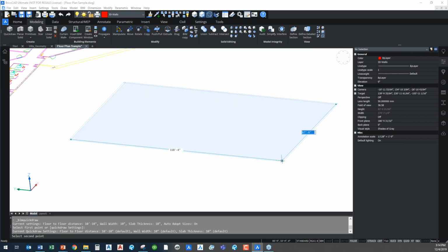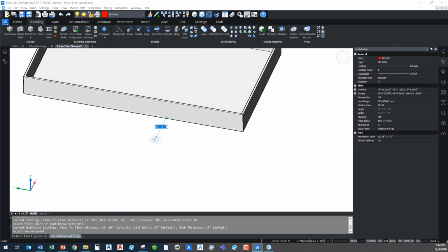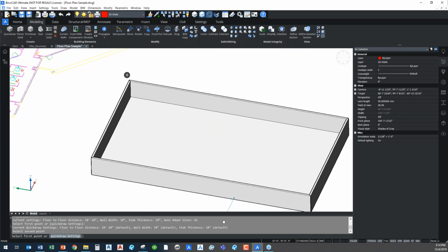So if I'm doing one area, if I'm doing a gymnasium or a warehouse, you see I can just tab using the tab key from side to side. So if I want this to be 65 feet on this side, and I'm going to make it 115 feet on this side, that sets my pad for me. And you see it's giving me some outer building structures, and I could have set the walls as I needed to for depths, and I'm just going to tilt this a little bit. Because now you see that I can go to each corner and continue out the interface.